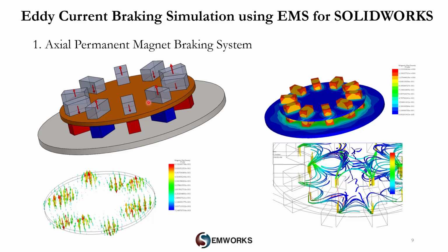We have now one magnetic loop from one pole to another pole of the same stator side, then through the air gap and the copper to the second stator side. This helps to increase the field going through the copper disk and reduce the used steel to make our system lighter. As you can see here, some loops. Here is a loop from one stator side to another stator side. The loop is now shorter, and the maximum field is going through the copper disk.